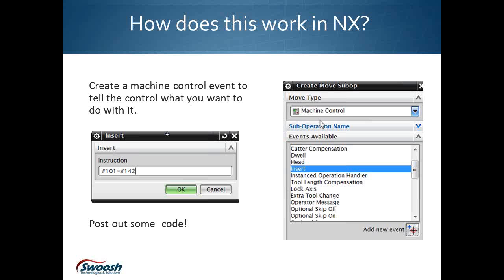And some people might think, well, who uses this? Well, there are people that live and die by this stuff. They're probing all the time, and in a past life when I was using an on-machine probe, as long as I calibrated it, I was able to get between 3 and 5/10 from the CMM results. So that's pretty good.